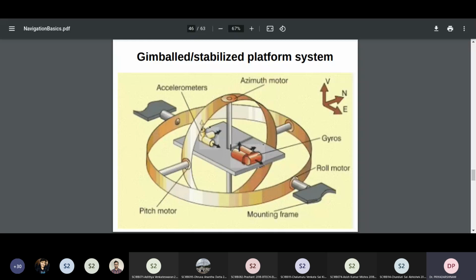These are all physical phenomena which we don't understand well, so they are only mathematically modeled. Drift is a major problem in these inertial sensors. That is why the integrated navigation system is finding wider application. You need an external source once in a while, and when that external source is not available, you should be able to do it yourself. Got it.